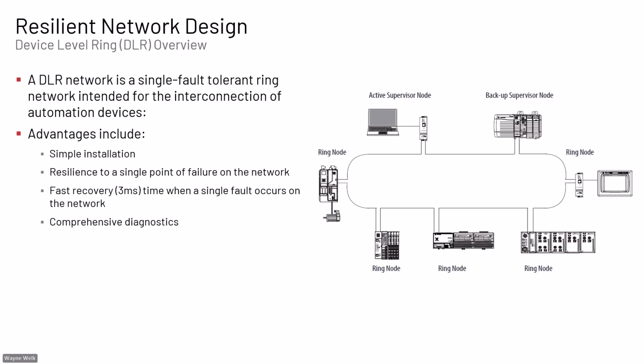Another great piece to it you're going to run into is the recovery time. There are plenty of other ring solutions out there. Some you're also familiar with, like you've seen REP, you've seen Spanning Tree. Those have recovery times, but not to the same extent that DLR does. With DLR, we're going to be pushing that 3-second recovery time, which for process applications and general automation applications is perfect, right? We don't want the moneymaker to shut down. And if it's a safety thing, we really don't want it to shut down.